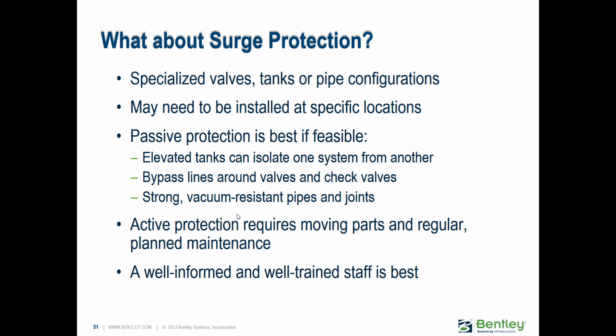So passive protection, as opposed to installing a new tank or a new valve or something like that, you can do other things like work with the elevated storage tanks. You can have bypass lines around the valves. You can have pipes that are just stronger or more vacuum resistant.